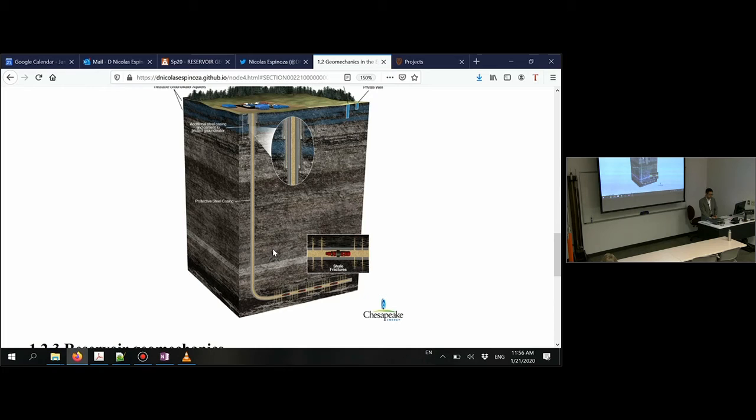We're going to see in geomechanics, almost from day one, how we use geomechanics for hydraulic fracturing, and that's going to be very useful to know in which direction we drill a wellbore and what are the pressures needed to do hydraulic fracturing, and try to understand a little bit better how those hydraulic fractures form and where they go.